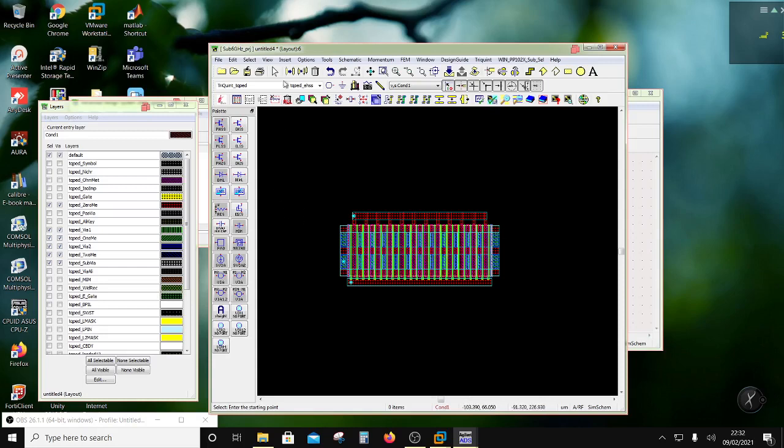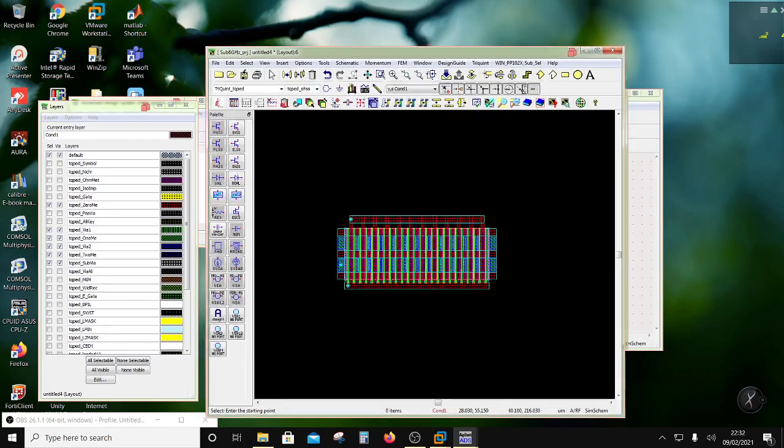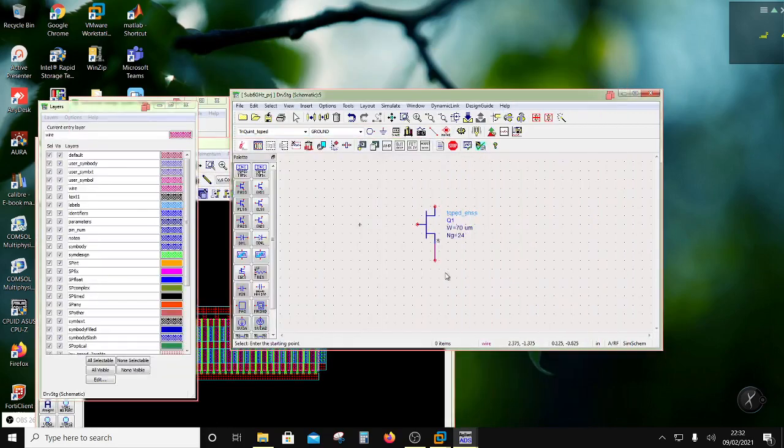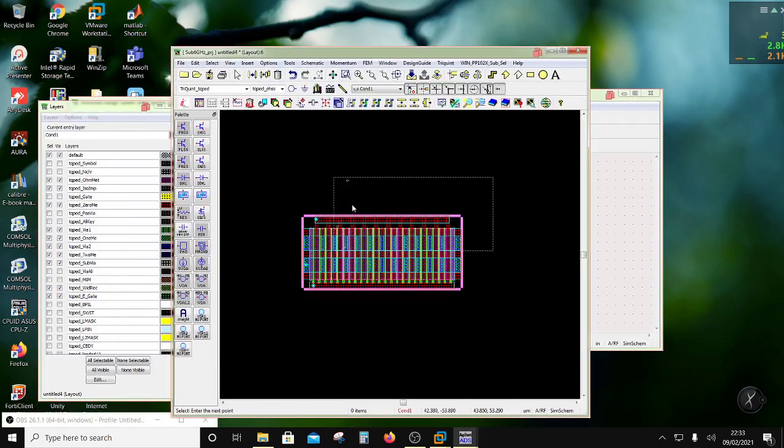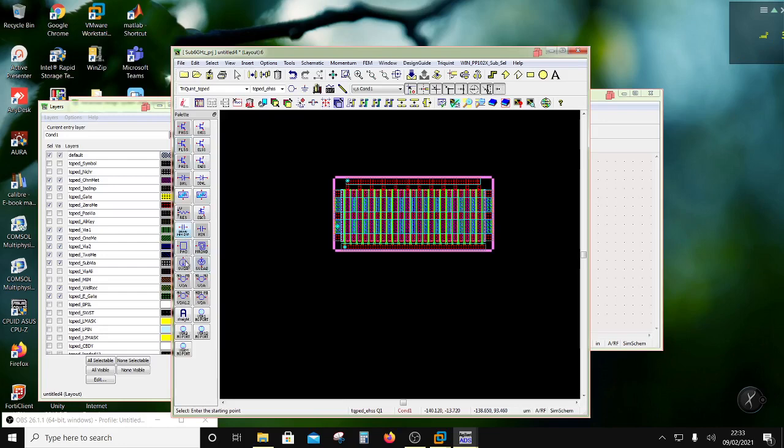The way they have modeled this device, if you see, there are 3 terminals. So they must have done the GSG probing. That means that the ground via is not a part of the model, so the grounding is not part of the model. If you directly put a ground here, it's impossible to create a perfect ground. So the device basically is going to see vias. So if I was to put a substrate via here,